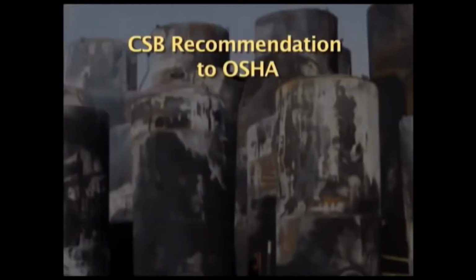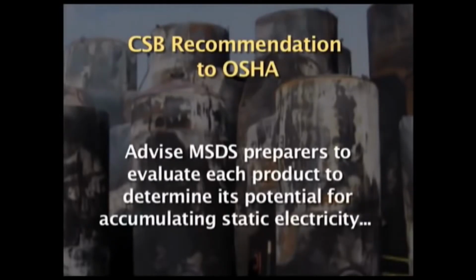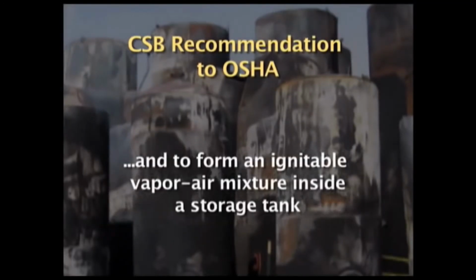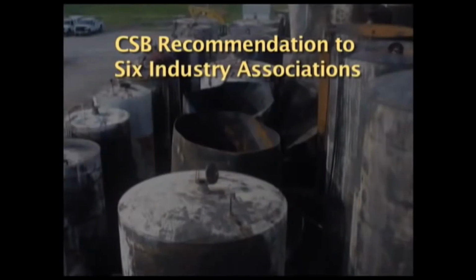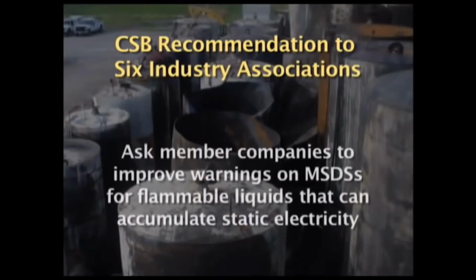The CSB recommended that OSHA advise MSDS preparers to evaluate each product to determine its potential for accumulating static electricity and to form an ignitable vapor-air mixture inside a storage tank. Each liquid should be tested for electrical conductivity, and the results included in the MSDS. The CSB also recommended that 6 major oil and chemical industry associations ask their member companies to improve the warnings on their MSDSs for flammable liquids that can accumulate static electricity.